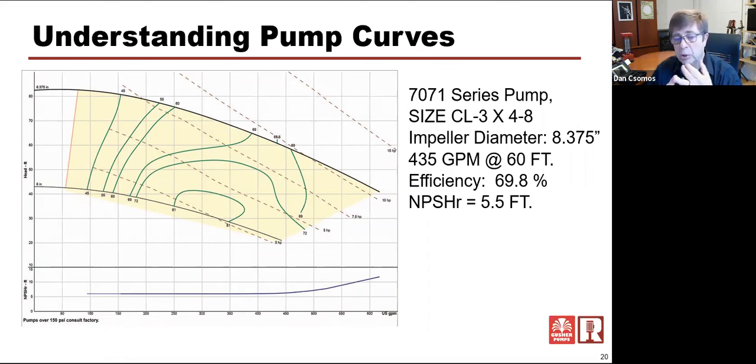If you read that pressure gauge and you come up with where you know, for instance, 70 foot of water would be 30 psi, or maybe 30.5 psi or something here, and that approximates what your amperage rate is, that's pretty much where you're operating on this curve. You know you're pretty close to that.